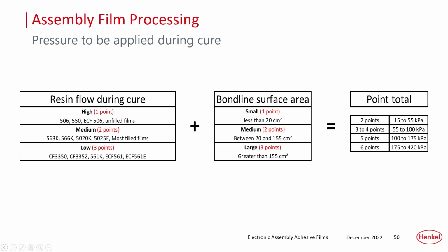So to build that into an assembly process, you need to warm the glue up gradually to allow it some time to wet out onto the surfaces before it fully cures, and then leave it for the curing cross-linking reaction to complete after the wet out phase. Typically the curing of these things is, like I said, an hour at 150, although there are some different formulations that will cure at lower or higher temperatures. Okay, on to the next one.